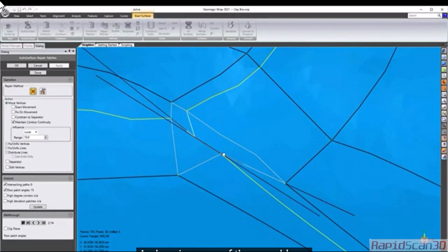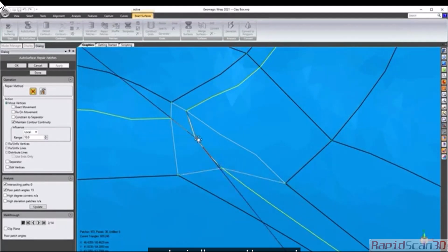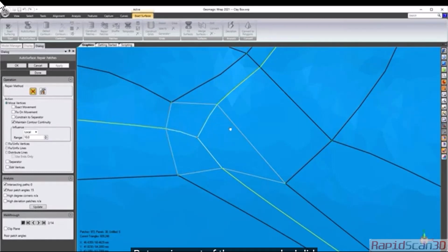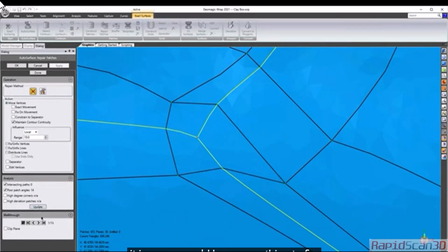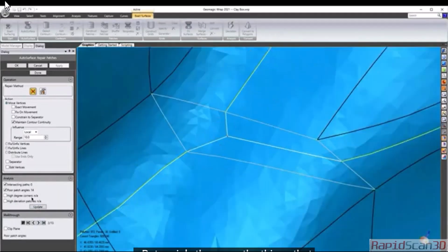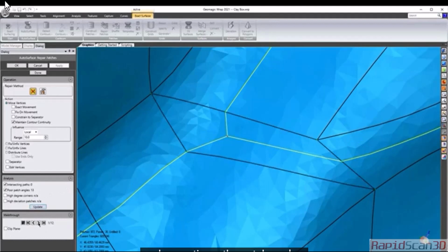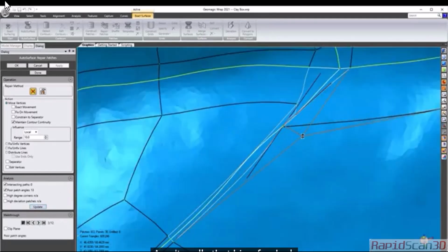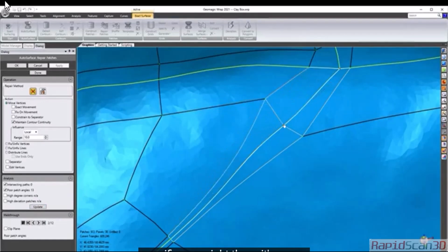And again, some of these problems are basically caused because I selected an algorithm that specializes in a different type of part. But part of the reason why I did it is so we would have something to fix here. Mainly, these are the things that it will find are poor patch angles. And many times the patch angles aren't really that big of a deal. Now, obviously in that specific case right there, it's going to have some surface wrinkles.